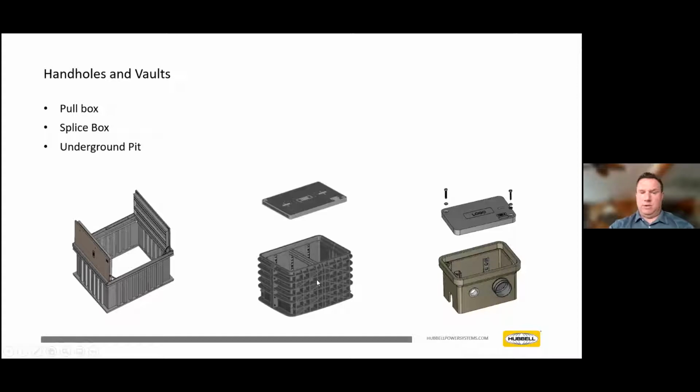The next image is a high density polyethylene plastic box. You can see a lot of reinforcing ribs within those designs. And that's supported with polymer concrete covers to meet the ANSI SCTE 77 standard. And then next is a traditional polymer concrete Quazite enclosure. So it's a polymer concrete base and cover to go with it. You can see additional features within that. Racking systems, terminators, pulling eyes would all exist within those.